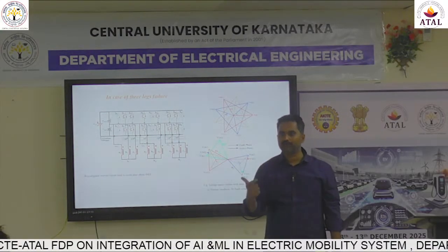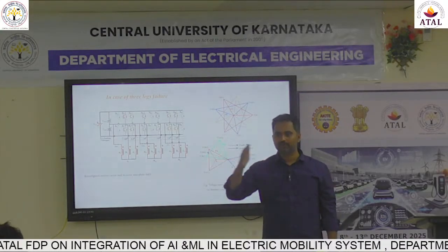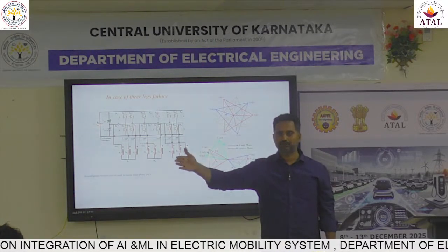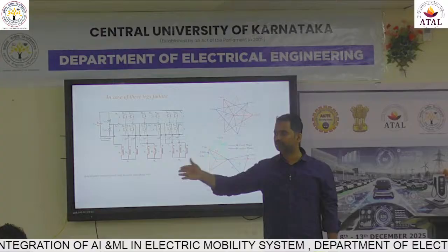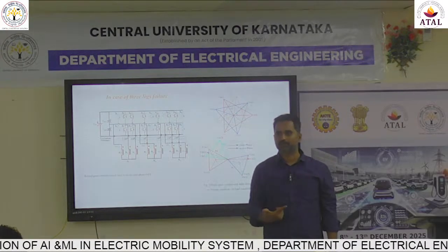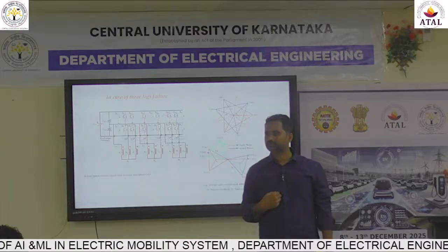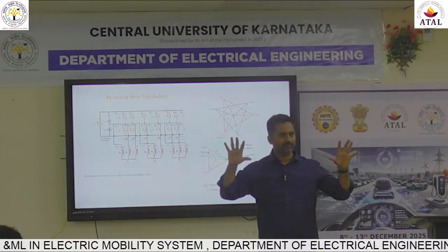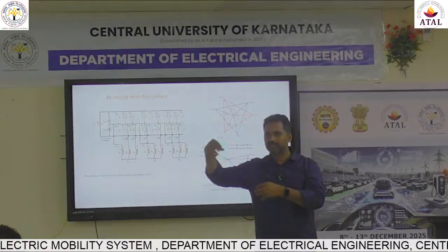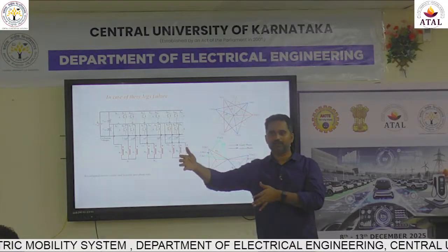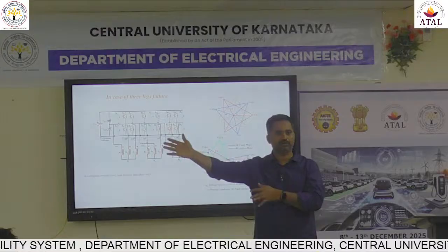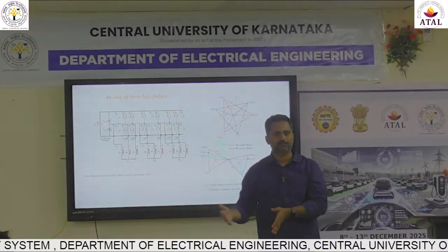I don't know how many of you remember the induction motor equivalent circuit. For ripple, what will happen? The secondary is short circuited. Then it's going to be huge currents. How you balance those currents is also going to be very important. If anyone of you remember, R2 by S will come in the secondary side. No, that is for the fundamental. For the ripple, what will happen? The power loss, we assume to be 0 for ripple. Just ignore that R2 by S. Then what will happen? That is a dead short circuit.